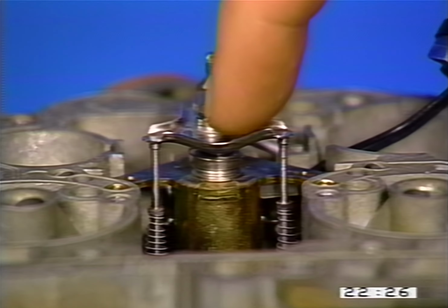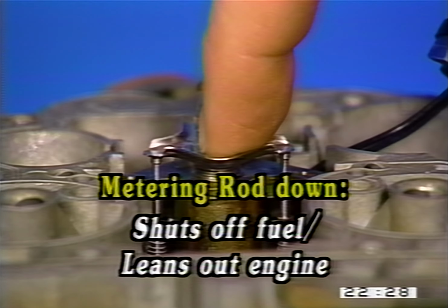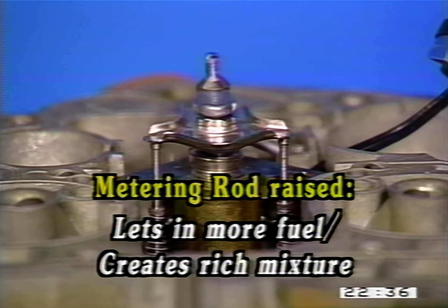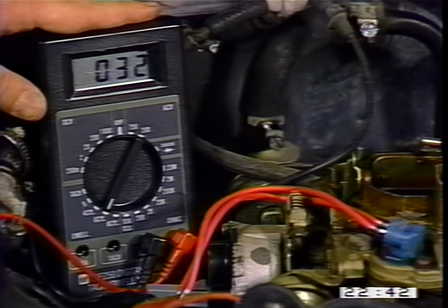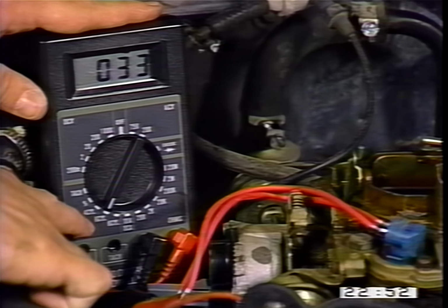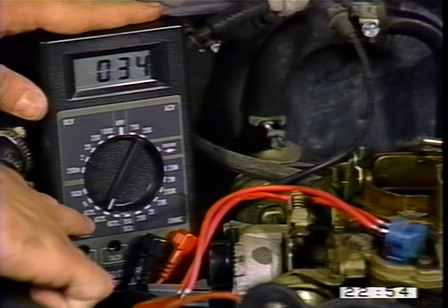When the MC solenoid is grounded, the metering rod is pulled down. This shuts off the fuel and leans out the engine. When the MC solenoid is not grounded, the metering rod is raised, which lets more fuel in, creating a rich mixture. When the duty cycle or dwell is changed, the ECM provides optimum fuel delivery rate for any need. The dwell of the MC solenoid should be, ideally, 30 degrees with the dwell meter set to the 6-cylinder scale.